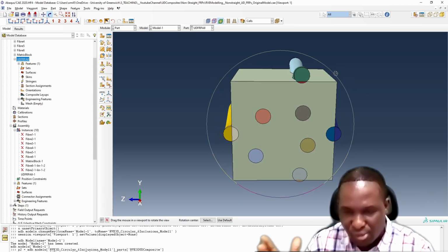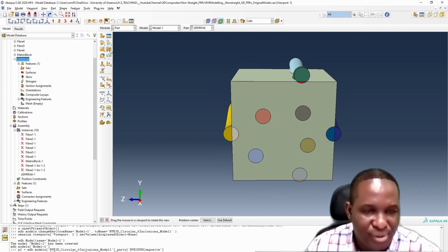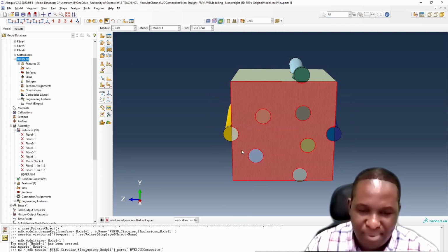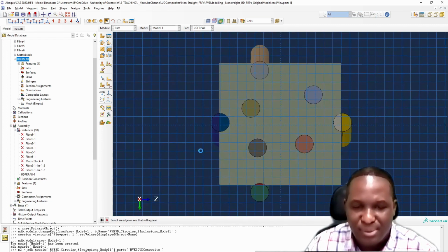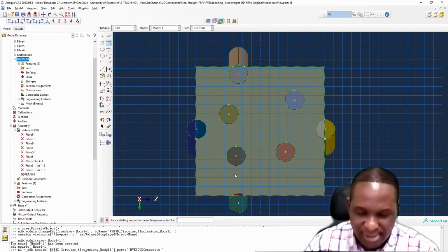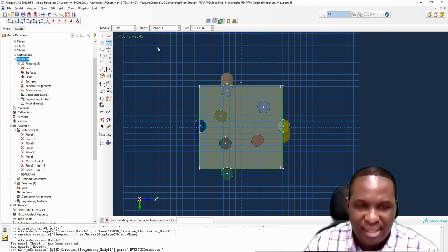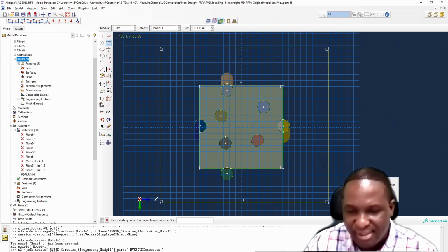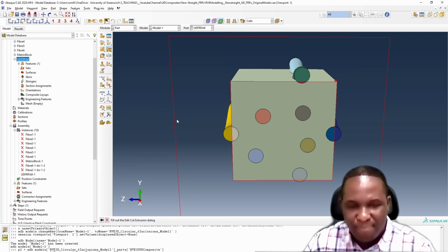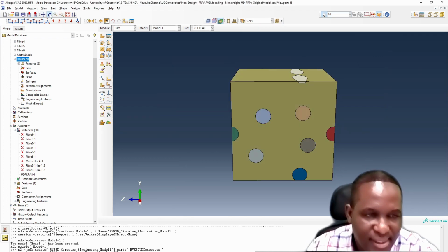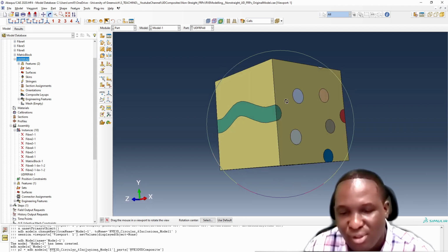So what we need to do is obviously to trim. We'll use extrude cut here, select this plane that we want to tweak. Then we'll create this first rectangle, and then a bigger one to encompass that, so that the remaining space will be extrude cut. So it cuts through the domain, and then we'll have a really lovely representation of our structure.